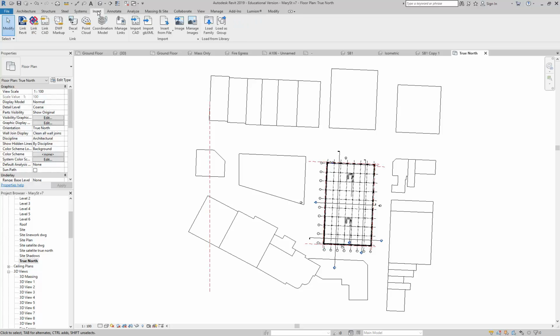So if you're not sure how to bring one Revit file into another, the only option, some of you have said it, is on the Insert tab, Link Revit. And then you can insert any Revit file into another file. So that might give you a little bit. But look, I know it comes up with the message, anything over 10 meg, it'll come up with the message saying it's going to slow down, but the computer is going to handle it with those files.